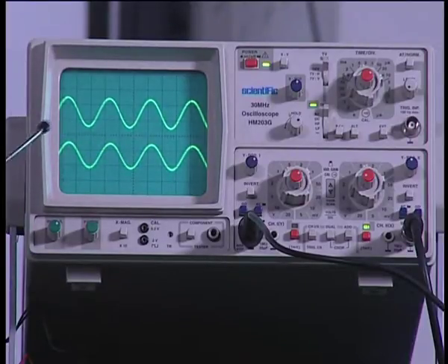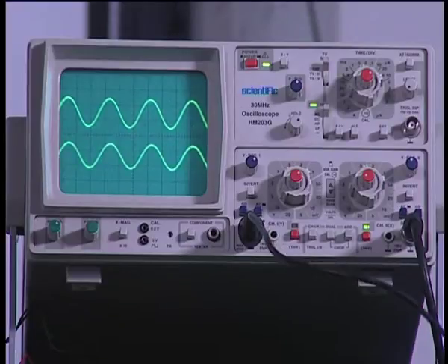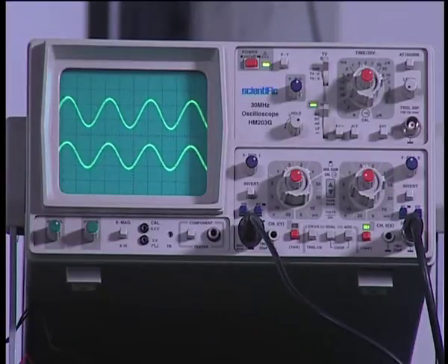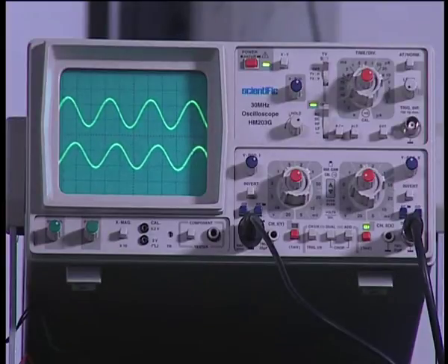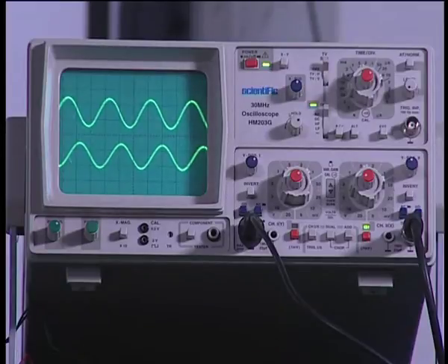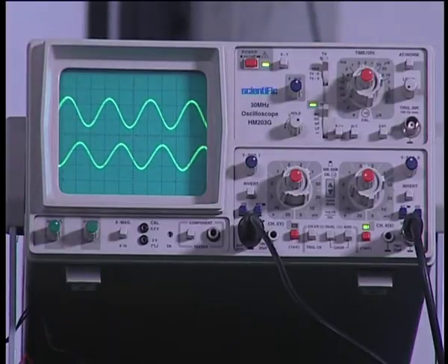Now, I want you to continue to observe the oscilloscope while I change the potentiometer, and you would find the trace slowly moving away. Right now, we can see that the trace starts moving to the right, and then I can go almost up to the 180 degree phase shift corresponding. Then I come back now, the potentiometer, now it is in phase. Now, as I move that, you find it is shifted towards the right, and therefore, the phase can be continuously varied from 0 to 180 degrees.